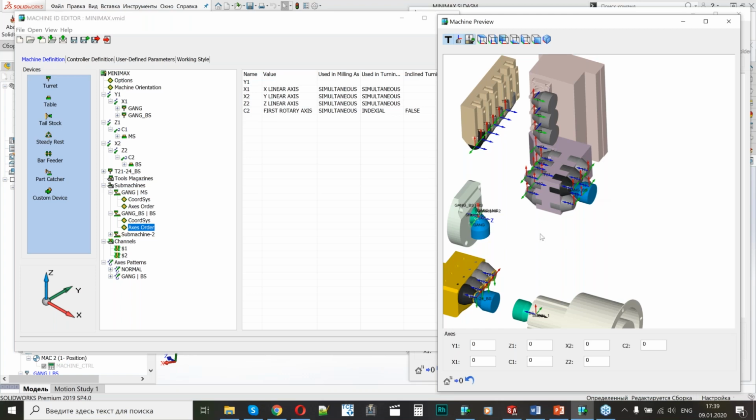Then I will call the tools, or I will call the tools first in position. It depends on the scenario which is used on a plant on each particular machine, and after that I can apply this mode. But before it should be applied, the subspindle should be positioned right opposite the tool which will be used. So this tool should be in its correct position. It should be, for example, in one line with the axis.